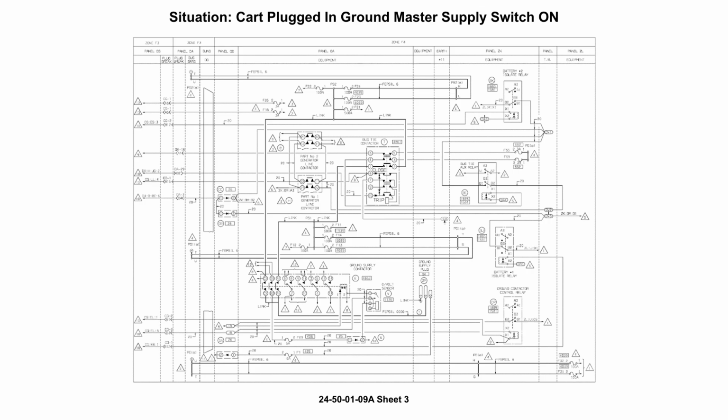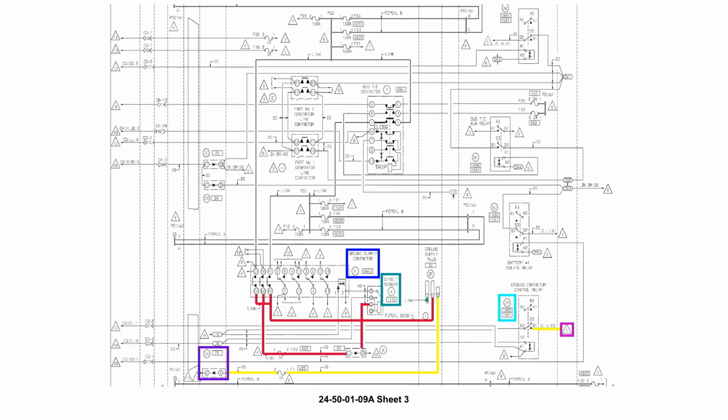We now return to the first wiring print, looking just as it did while the ground supply master switch is in the off position. When the supply master switch is moved to the on position, power should become available at pin X1 of the ground contact control relay, and a ground signal should become available on pin X2 of the control relay, as well as pins Golf and Papa of the overvoltage sensor. If the sensor reads good voltage on pin Sierra, the ground signal at pin Papa will travel out pin India and to pin 2 of the ground supply contactor.